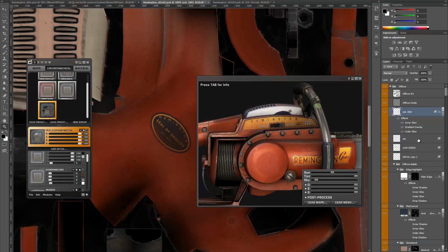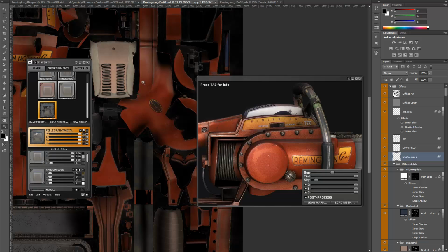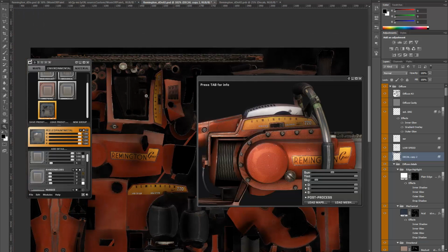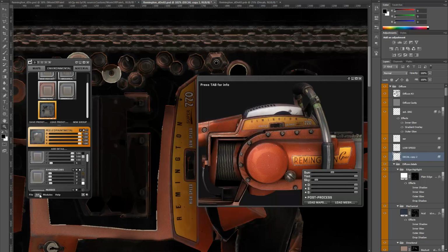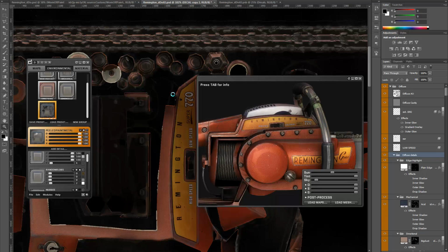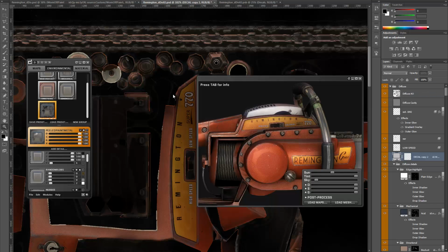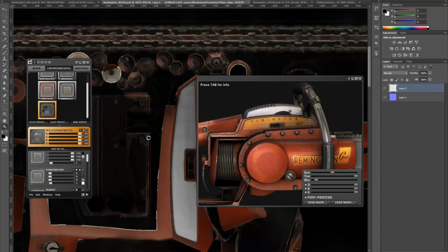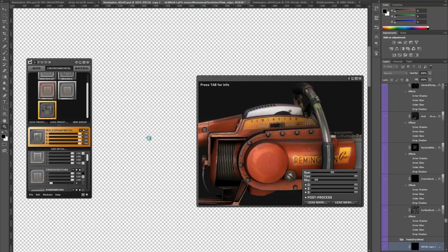And first of all, I'm going to select, let's see here. I'll do one at a time. This one here. So with that layer selected, I'm gonna go into Edit and Detail from Current Layer. So now I'm going to be able to control the reflectance values in the diffuse, gloss, specular, just like all other details.